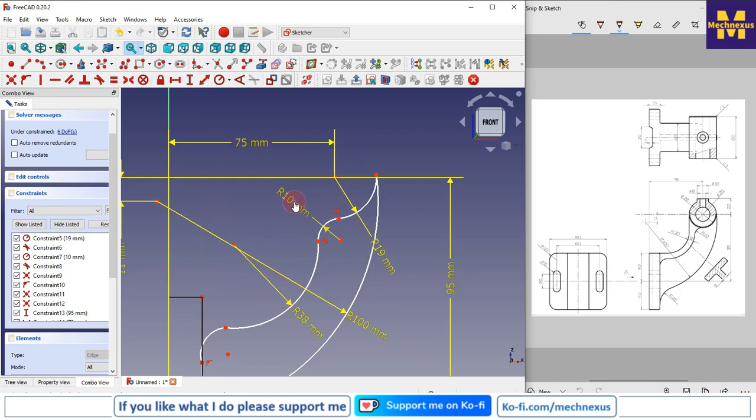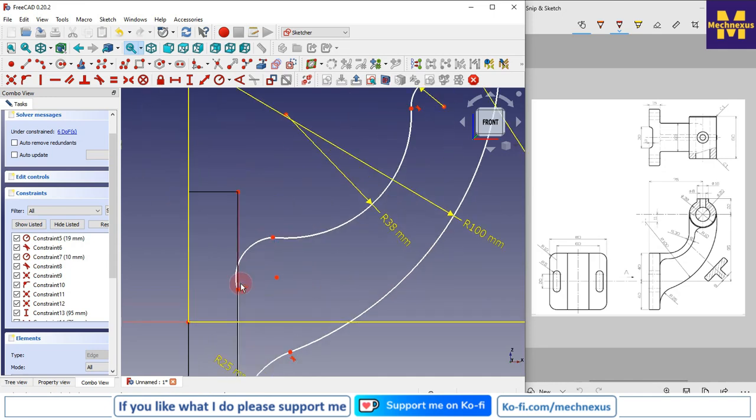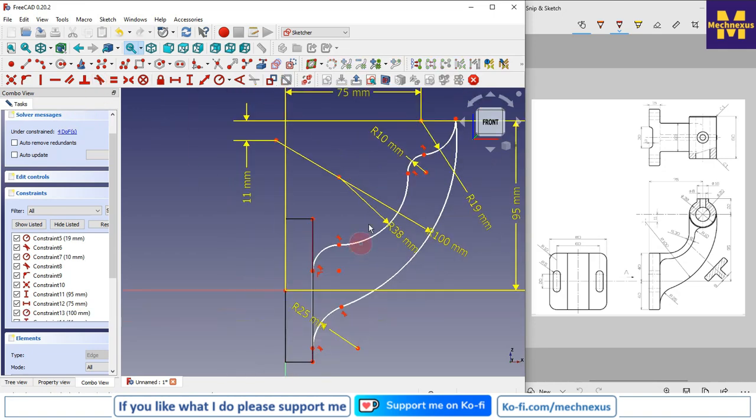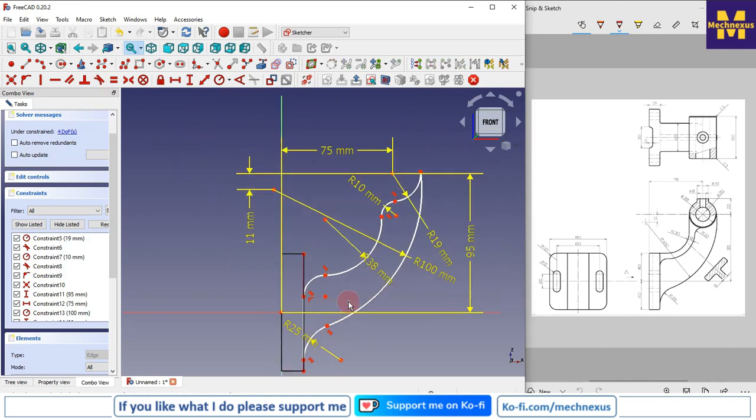I will move the 10 mm outside. And here I will make it tangent to this point, and this one make it tangent and tangent. Now we have given 25. Now we will find out the degree of freedom of each one.